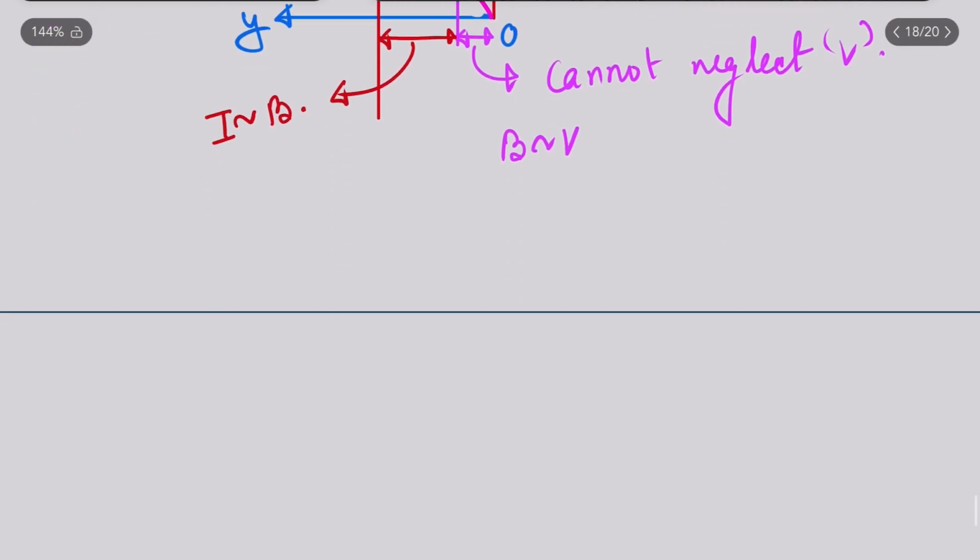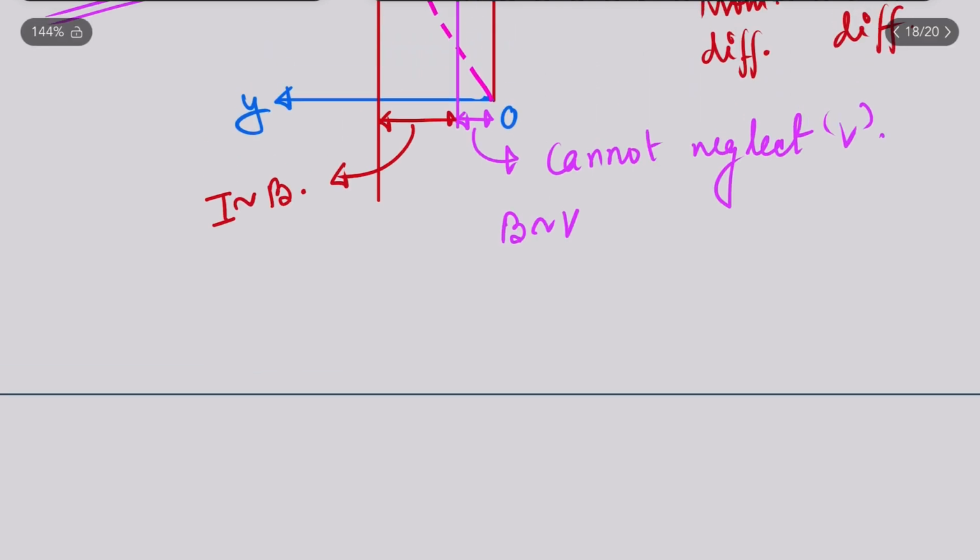In DRDO I was precisely asked in the interview what is Prandtl number and what is its significance. Like any other aspirant, I told that it denotes the ratio of the hydrodynamic boundary layer to the thermal boundary layer. Then they asked me to tell the difference of individual things like alpha and nu. Then I told that alpha defines up to how much distance the thermal nature or the temperature will be propagated, and nu decides up to how much distance a momentum disturbance will be propagated. So these kinds of understandings are very necessary.